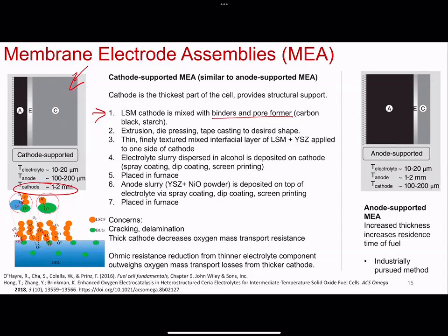So you can target, let's say if you want 10 nanometer pores, you pick a polymer whose chain length is going to be of that size. If you want bigger pores, 50 nanometer pores, 100 nanometer pores, then you pick longer chain polymers, maybe even branched polymers, but basically your polymer chain length is going to be longer. Then when that burns off, you get larger pores. This is pretty typical for ceramic engineering, where you pick something sacrificial to template essentially. So that's what you do.